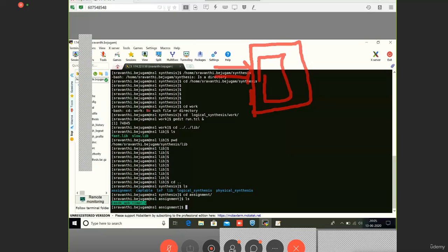Inside this APB slave, a state machine will be there, and there is a timer counter which will be running based on the register set. Some registers are there. Load the counter, and from that, it will start decrementing. Once the timer comes to 0, then an interrupt will come, the interrupt output. Also, an external clock can be supplied to the timer.